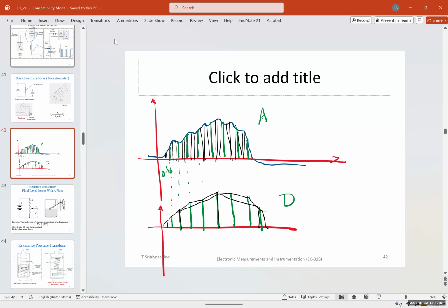A higher sampling rate means if I double the sample rate, I'm going to double the data. And if you're going to send this a long distance, like an image that you want to compress and send on the internet, you don't want a high sampling rate. Up to a certain point, it gives you information. After that, it's redundant. And below that, it eliminates a lot of useful data, and it becomes useless. So you have to find the sweet spot on the sampling rate.